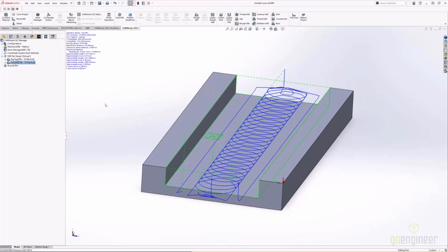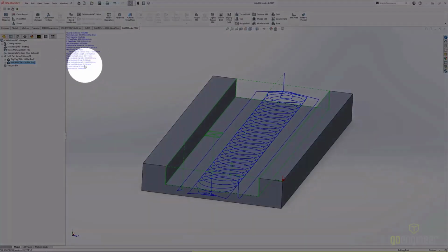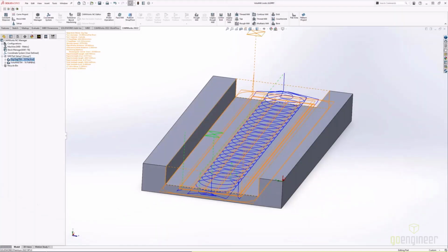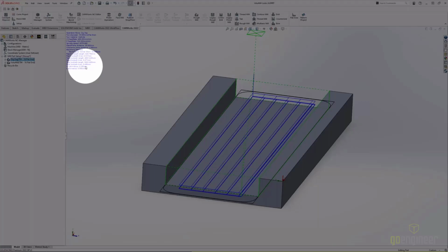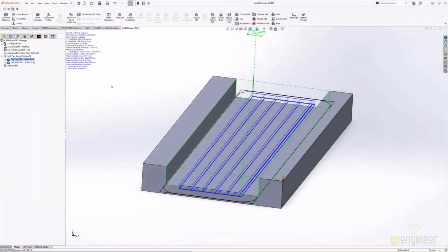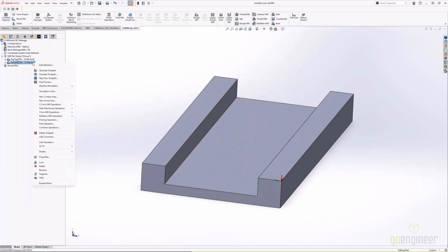So these two separate patterns are going to remove the same amount of material, they're going to go all the way through your part. They are not your finishing passes, but they address it in totally different ways. If we look over here, we can see that this is set to 5.292 minutes, and the zigzag is set to 9.488 minutes.